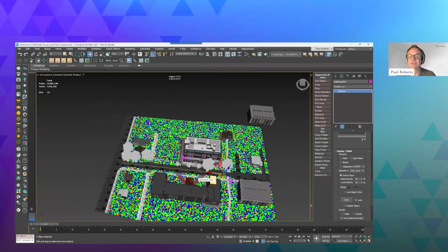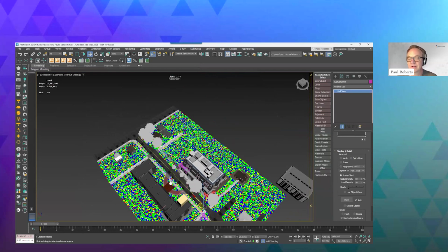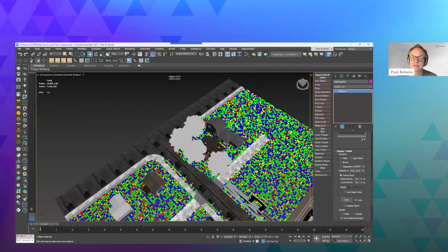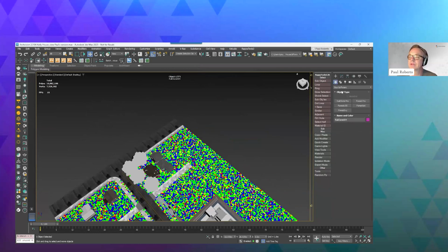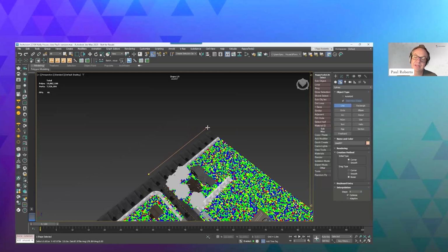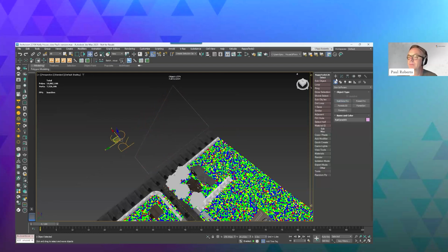When it gets really interesting is when you get to the advanced RailClone styles. For example, we might want a background building here. We could create a background building there. We can make it any shape really. Maybe it's a bit like a wedge shape. And then we can open an object in RailClone.